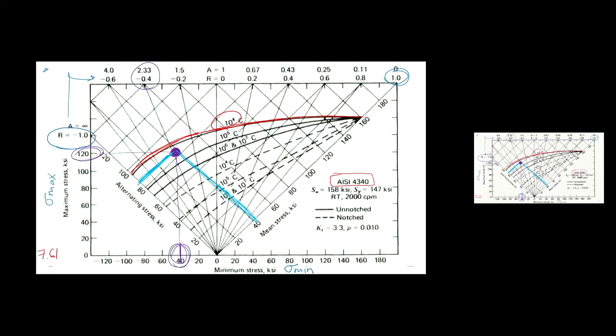So if I have that exact stress state in AISI 4340 and cyclic stresses, I could expect my sample to last greater than 10,000 cycles, but less than 100,000 cycles, because the curve right below that is 10 to the 5. So I've got between 10 to the 4 and 10 to the 5. And I could interpolate if I wanted to make a better prediction. It's about halfway. And then the curve below that says 10 to the 6 and 10 to the 7.